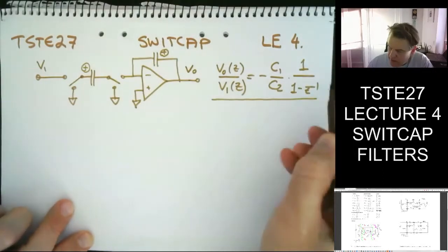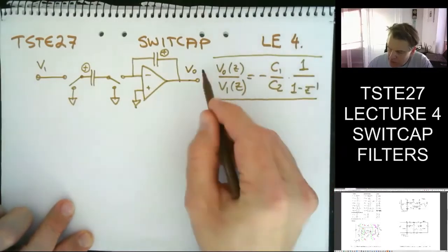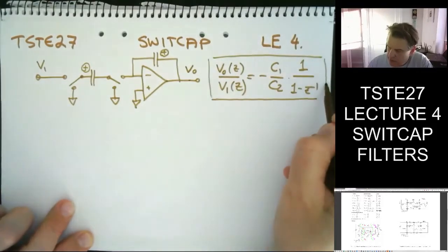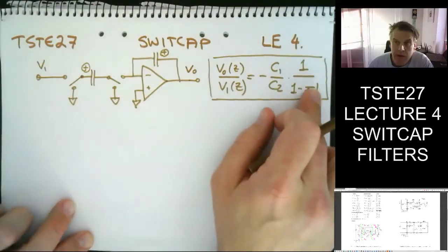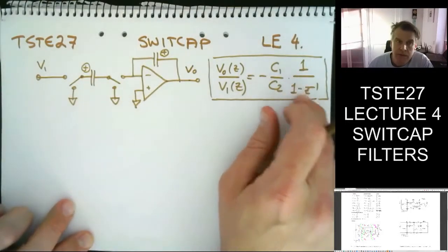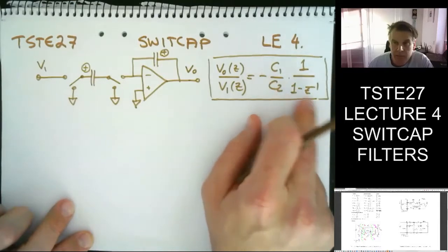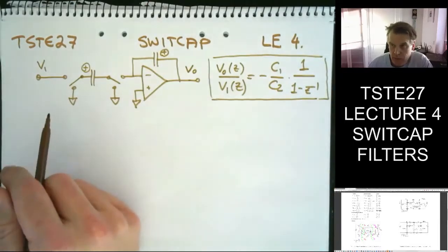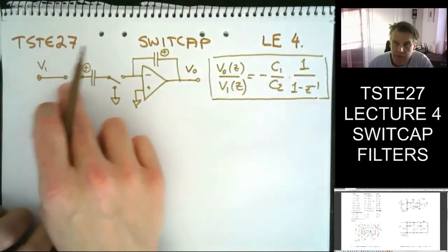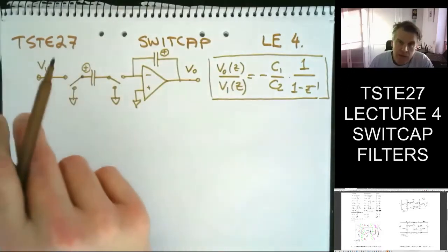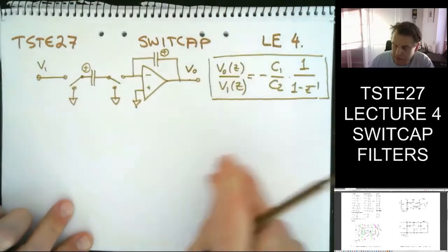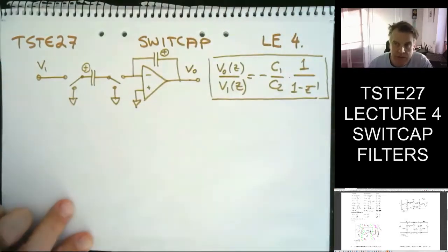That's a standard equation or transfer function in the Laplace, in the discrete Laplace transform, the Z transform of an accumulator, an integrator, something that adds and multiplies on top of itself. So if I would add something like a DC, or like a number 1, I would get 1, 2, 3, 4, 5, 6, etc. multiplied with this C1, C2, something like that.